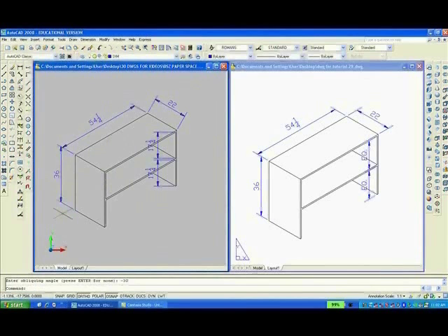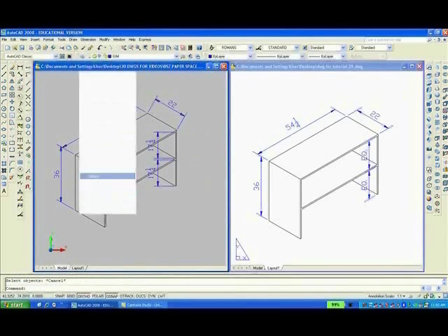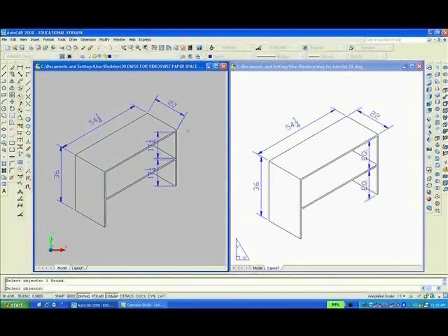And then we have to oblique again, O enter for oblique, select this one. But this is not a -30, this is a +30. So just type 30, enter. Didn't work. Try it again. I'll go to dimension, I'll go to oblique, select this one, enter, 30, enter. That seems to be okay.